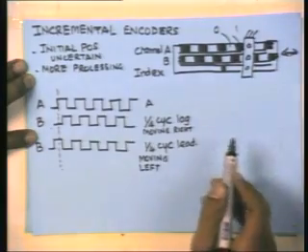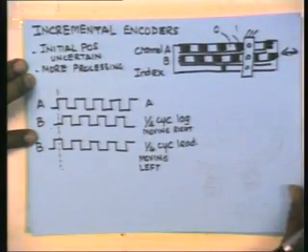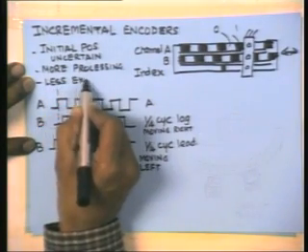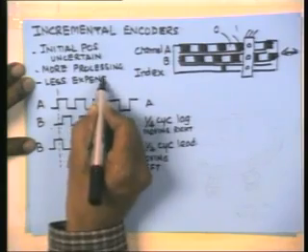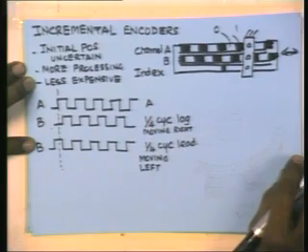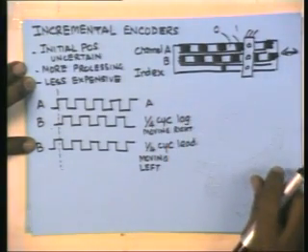In the case of an absolute encoder, you just read the photodiodes, and depending on the pattern you immediately know where you were. Here you have to do some processing like counting. You have to determine the direction, see which way you are moving, and keep track of where you are. But these are of course much less expensive, because they are of much simpler construction. You only have 2 tracks, and those 2 tracks are enough for you to determine the position.